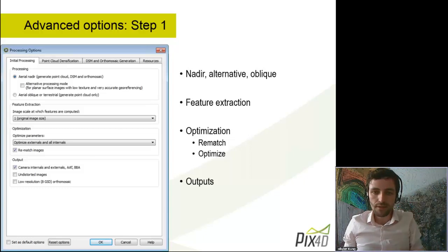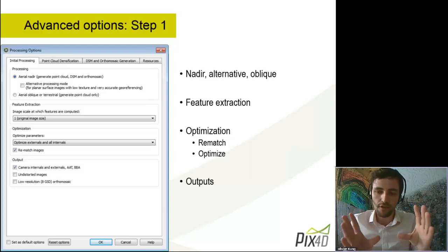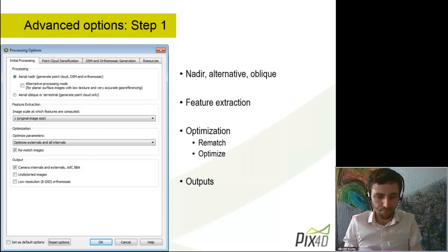However, in some cases, you would like to tell the software not to optimize all the camera distortion. This is especially true when you have cameras with a slow rolling shutter speed, which causes effects in the images that confuse the algorithm and may lead to failed processing.